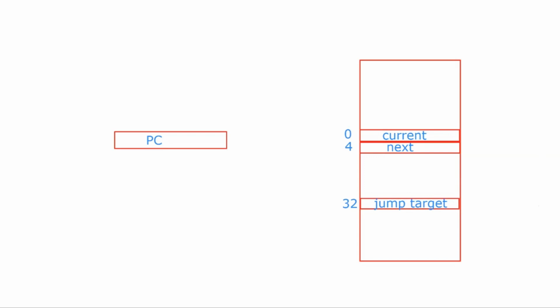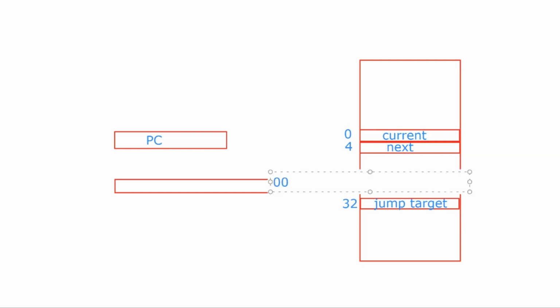In a typical byte address, the least significant 2 bits are always 0, because each instruction takes 4 bytes in memory: address 0, then 4, then 8, and so on.